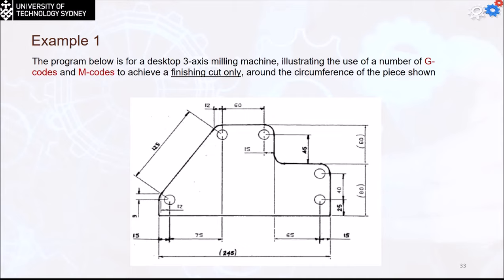That means we did all the cutting, we have this final shape, and what is left is 1 millimeter on the side to be removed. That means my cutting path is going to be offset from the final length, because we are going to cut 1 millimeter off from this circumference to have the final dimensioning.